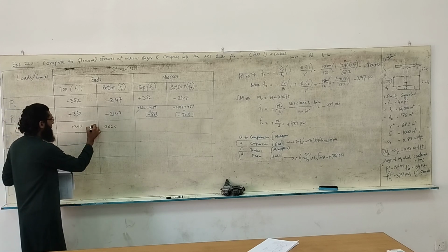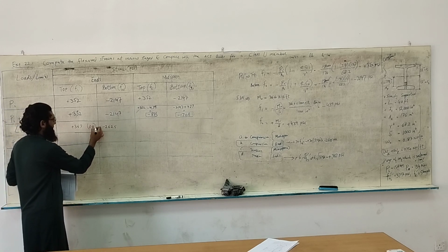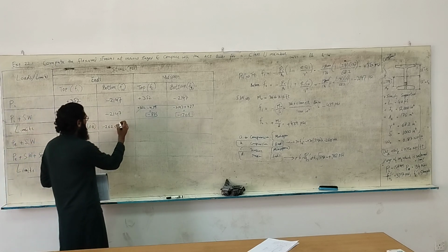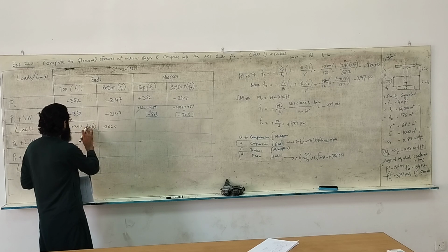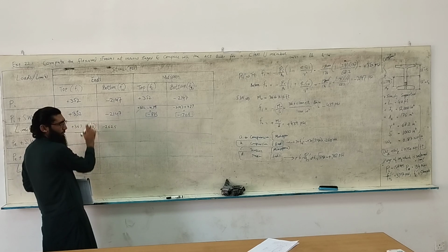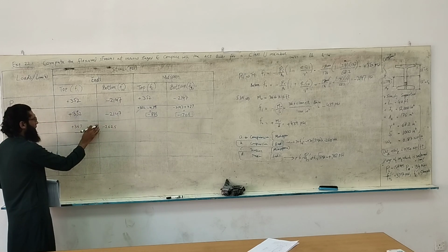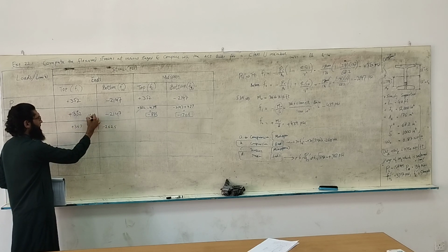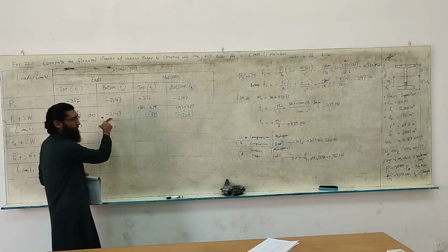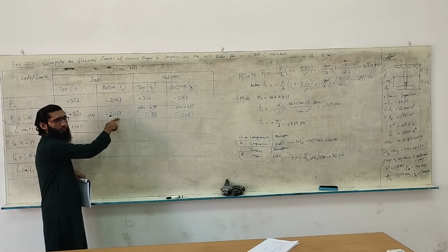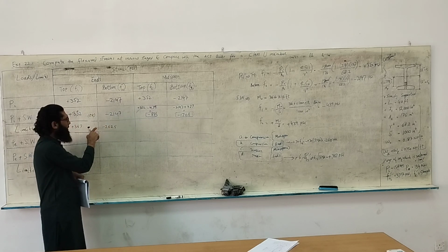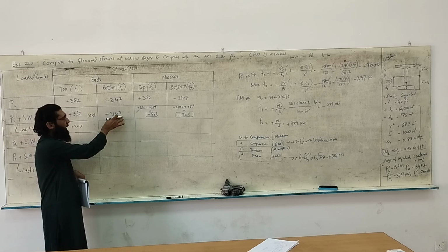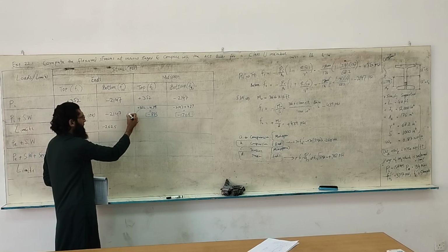Maybe you can put something that relaxes you. Okay, so you can just go ahead. This is okay. And what about the next one? Maybe you want to put the okay over here, because you're just saying this is okay because it is lower than the limit. All right. Now, what is this? What does it say? Minus 2147. Minus just tells you the compression, and this minus is also telling you the compression. Now, the maximum compression allowed is 2625, and we have lesser than that.